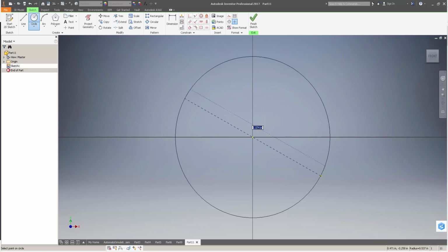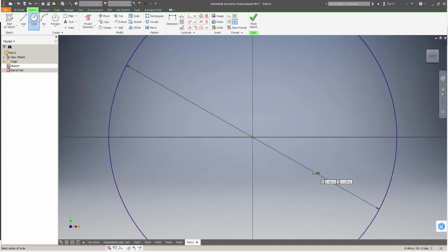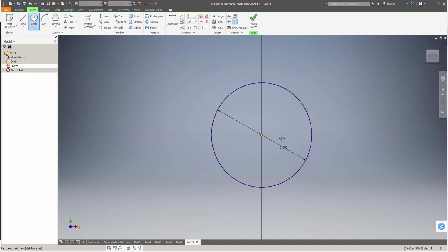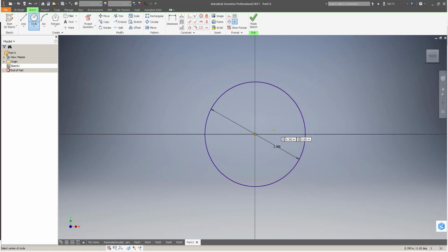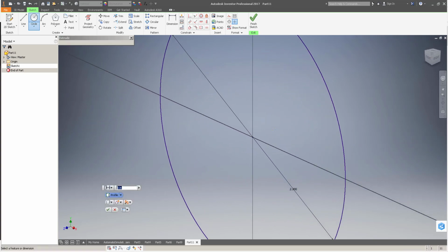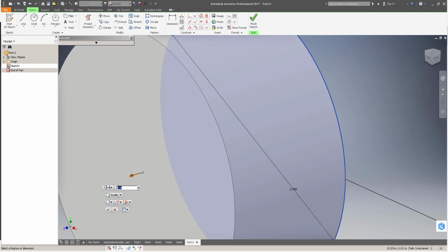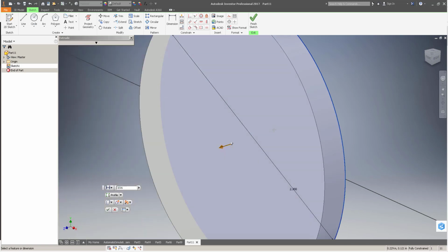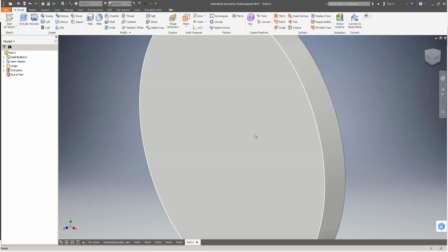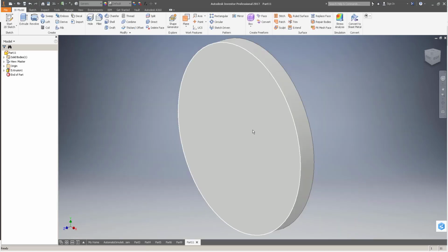Draw our circle out. Now our circle diameter is the nominal diameter of our cam in this case, so if I'm using 2 inches as my nominal diameter, I will have a 2-inch diameter circle. Once I input that, my sketch is fully constrained, so I'll hit E to extrude for shortcut key. Remember, Inventor loves math, so I'll allow it to do the 3/16 of an inch thick. And we have the main body of our cam.